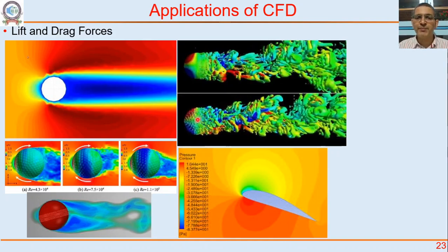These are vortices behind balls, a smooth ball and a rough ball, a golf ball. You see, the flow has become turbulent. The laminar boundary layer has become turbulent. It can withstand adverse pressure gradient better, so boundary layer separation is delayed.